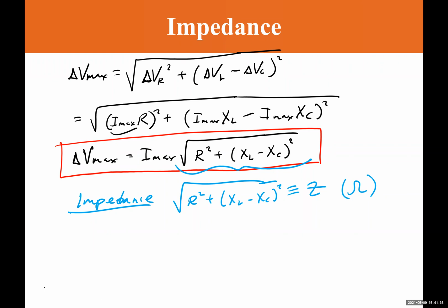This is the impedance equation. Because we have a resistor, capacitor, and an inductor in the circuit, the overall opposition to the current is not just in terms of resistance, but also because of the unique relationship that the inductor and capacitor have to the current, in a way that they act like devices opposing the current. The impedance takes into account not only resistance but also reactances.